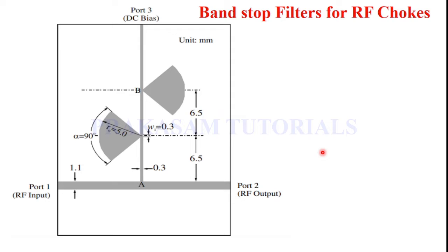And the basic bias network. What is the bias T network? A bias T is commonly used for feeding DC into active RF components in such a way that RF behavior is not affected at all by the DC connection. So bandstop filters are more effective as RF choke than low pass filters, due to the limited frequency band of RF active components.